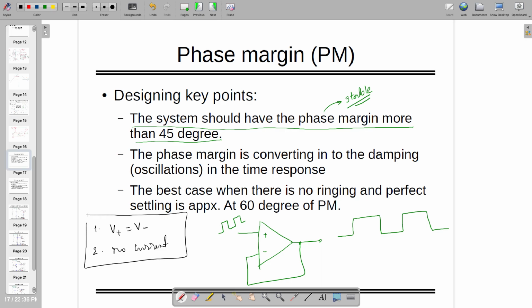And this will work only in the case that the gain of the amplifier is infinity. If it is not, then we'll study that also afterwards. So what you are going to get here is the same output, right? This is an analog buffer, so that you can drive the next part. The output should be the same, but you are not going to see the same, you are going to see something like this, because it's passing through the transfer function of this amplifier.